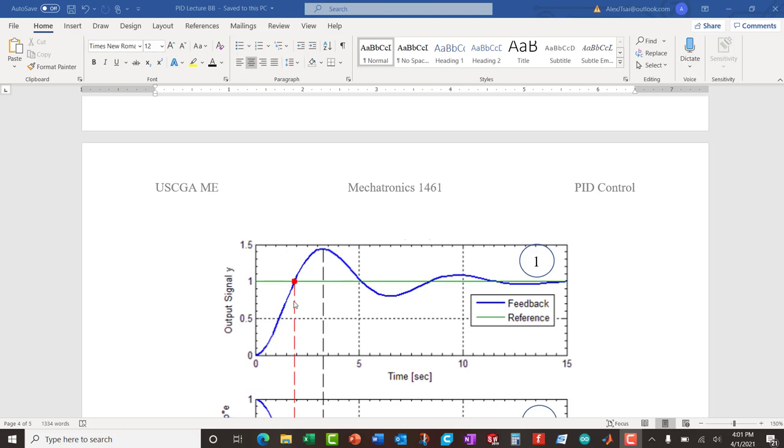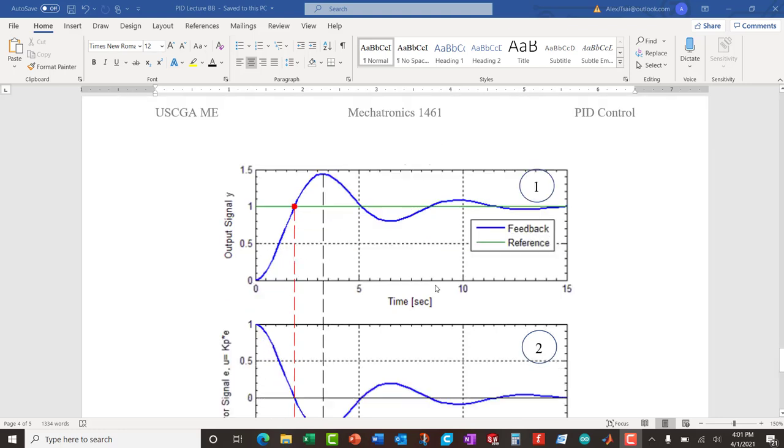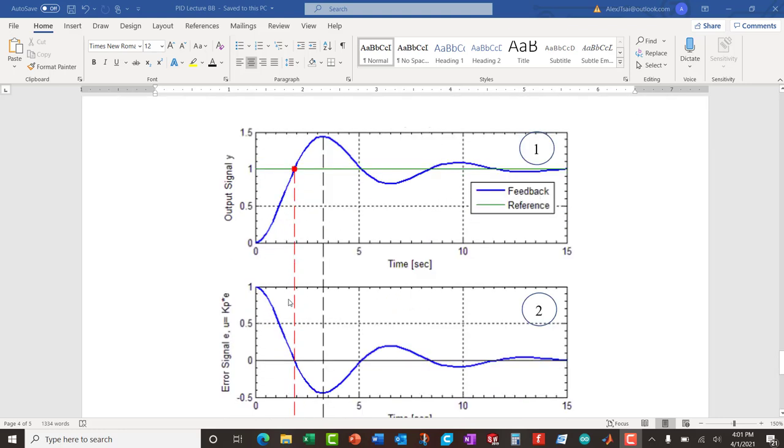Now, in this case, I jotted down or rather simulated this blue line as proportional control. That would be if I had proportional control, which I already explained. It's not really the case here, but let's assume it is. That is plot 1. Plot 2 is essentially capturing the error signal. So the error will always forever be the difference between reference, which is the green line, and the blue line at any given point in time.